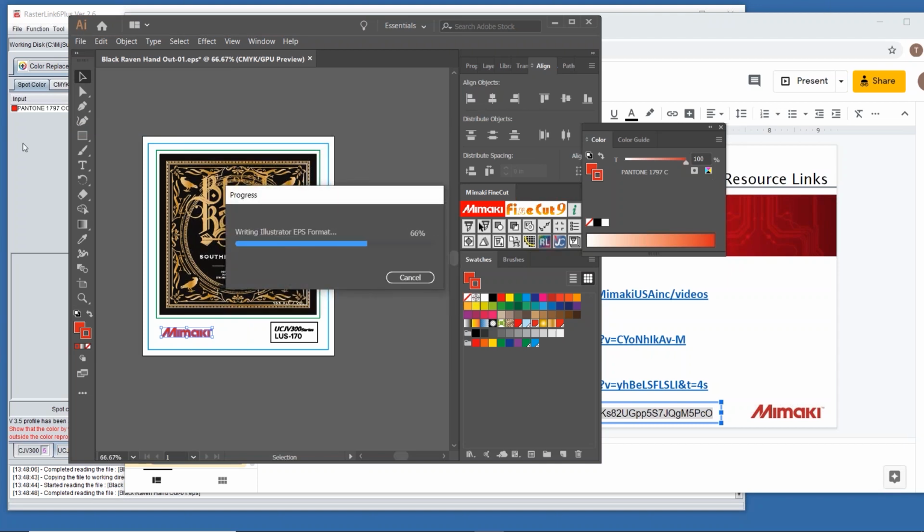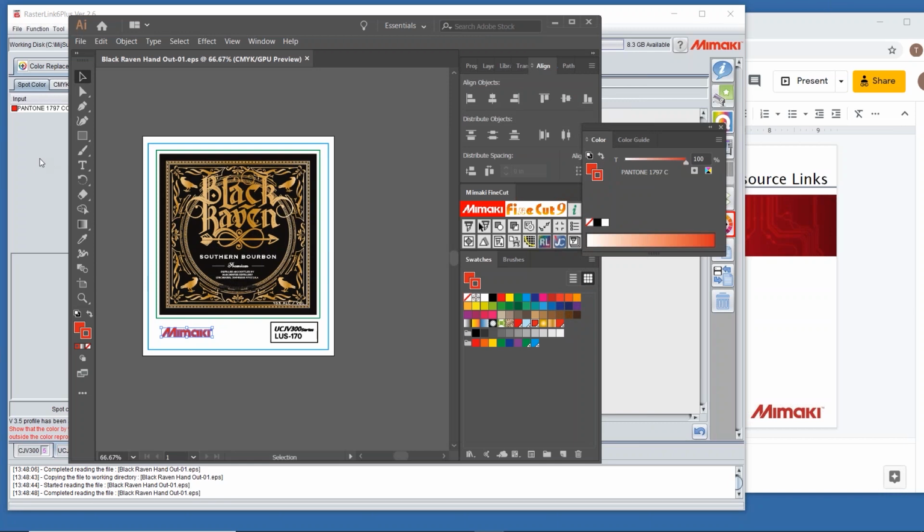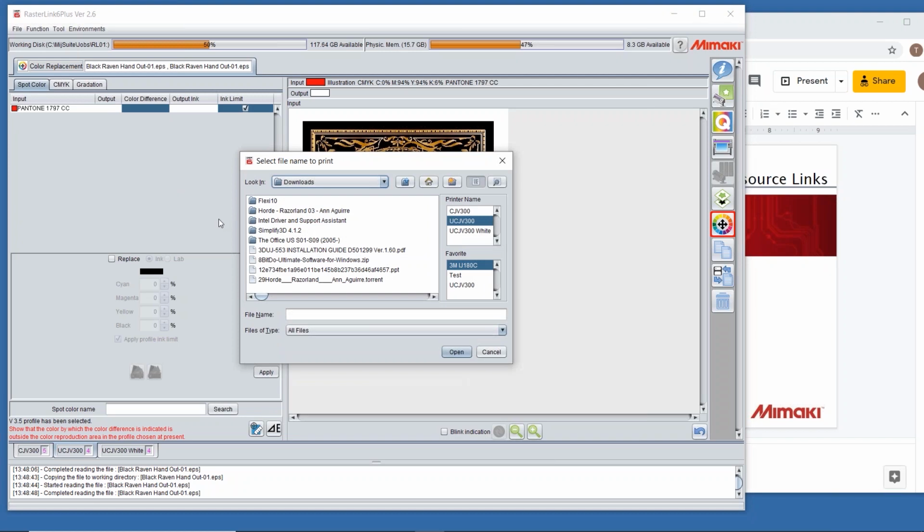While I'm needlessly playing around with the computer, are there any other questions up there? Sarah is asking about achieving square corners on cuts. The biggest thing I look at is if you're using a roll-to-roll cutter, make sure the offset's correct. So I would do a 1 inch by 1 inch, just straight cut square, fire it off, and try it with an offset of, I'd do like 0.2 and then 0.4, 0.6, and 0.8 for offset. Take a look at and see which one's got the squarest corners. And then from there, you may need to get down to whether it's 0.7, 0.8, 0.9, and you can even go so far as like 0.785 or 0.8.